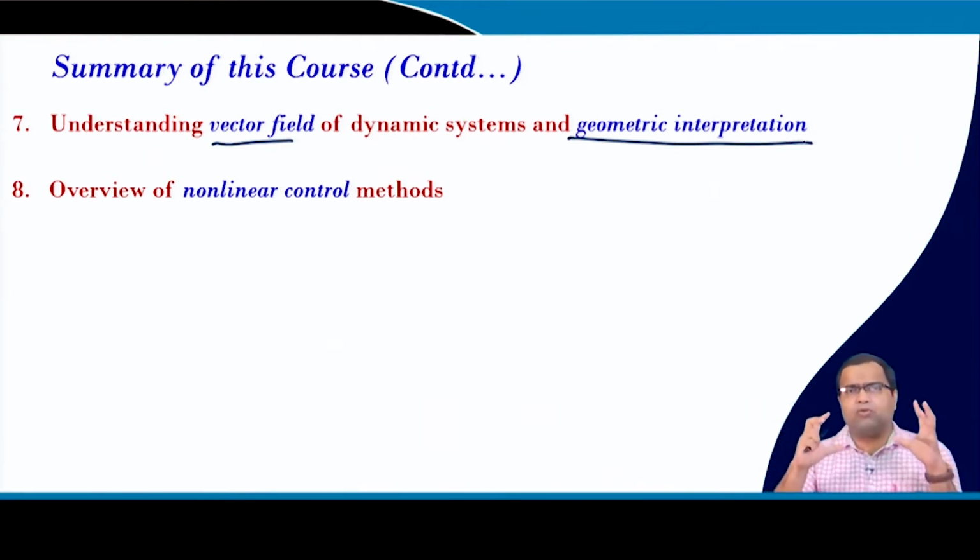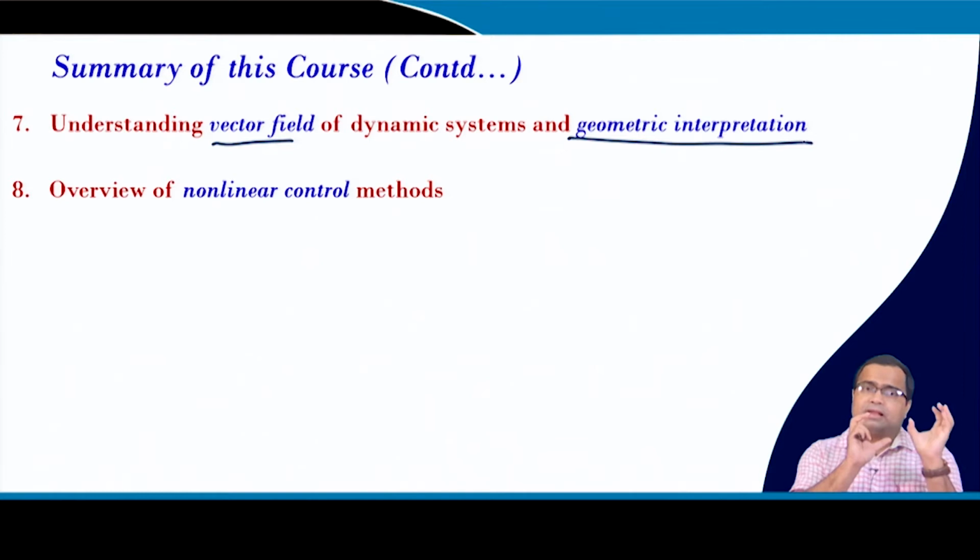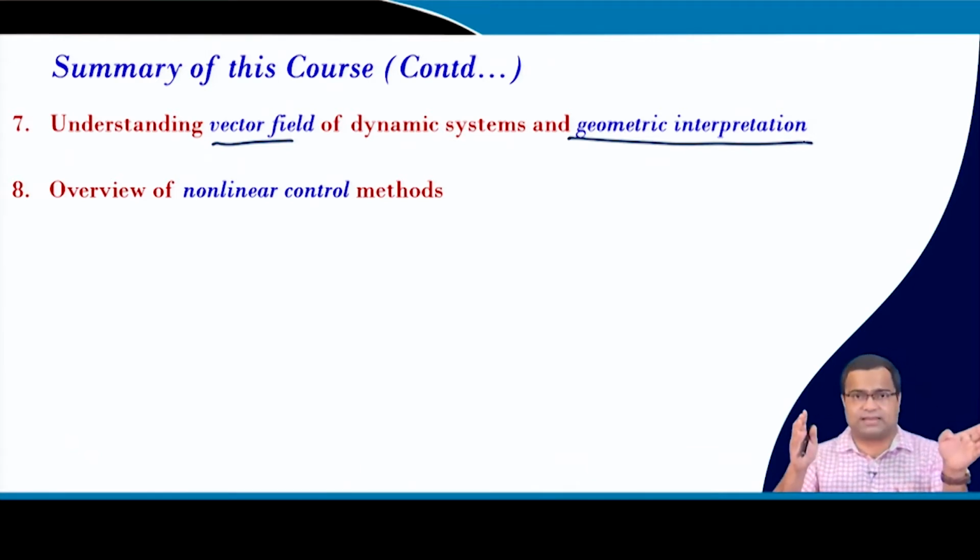Then we saw how to apply the gain scheduling technique in order to take full advantage. So, gain scheduling is nothing but a tuning approach, online tuning, where we need to update the controller parameters as and when the operating point changes, because then the location of poles and zeros of the transfer function may get affected. We need to update the controller parameters so that we can get optimal or at least better performance than the conventional design based on offline criteria, in which we generally consider the worst case scenario, design the compensator based on the worst case, and then plug in the controller value at the very beginning.